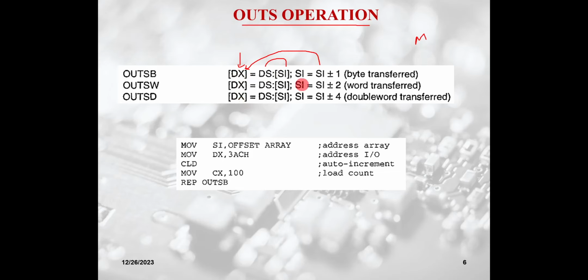Now remember, never does it happen that this data is taken from the memory and directly pushed into the port, okay. It cannot happen hardware wise, okay. Although this command is written like this, so this is a complex command, but in hardware implementation, okay, the compiler will break this command.